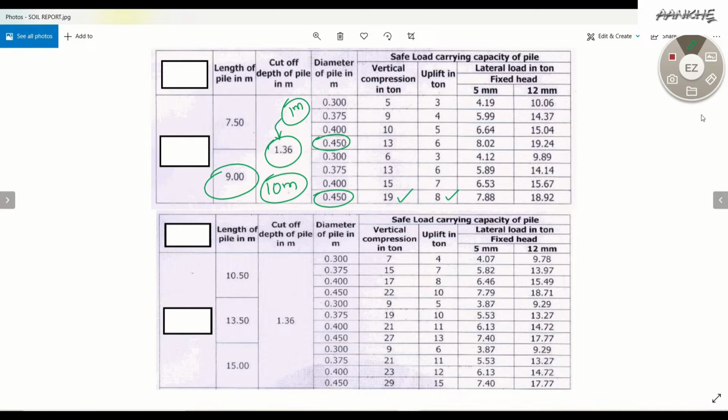In the upcoming webinars I will be explaining the fixed head type and what it means. You just imagine that a pile in a group and tied with a cap is assumed as a fixed head pile, otherwise a freestanding pile is assumed as a free head pile. In this case the allowable fixed head deflection is 5 mm.